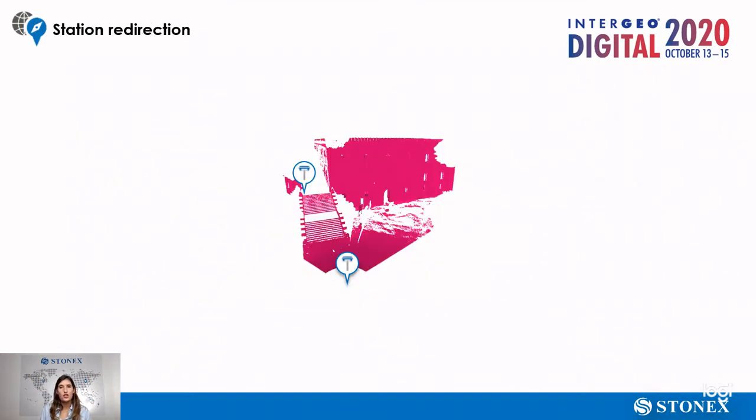Then there is the station redirection. For that tool, you need to know the station position, and you need to know another point that is inside your scan, inside your point cloud. So you will tell the software to do an orientation to this other point that you know.